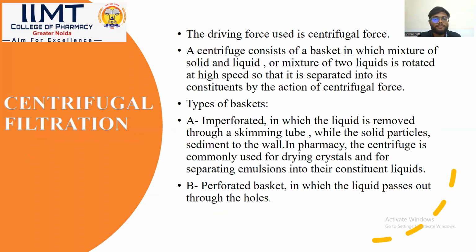Last one is centrifugal filtration. The driving force used is centrifugal force. A centrifuge consists of a basket in which a mixture of solid and liquid or a mixture of two liquids is rotated at high speed so that it is separated into its constituents by the action of centrifugal force.